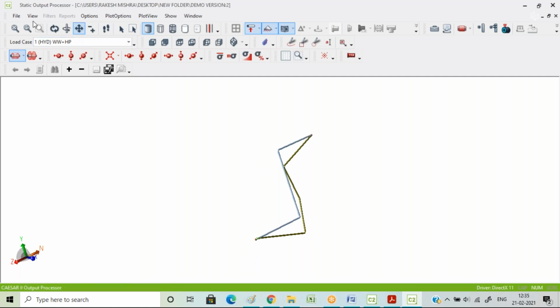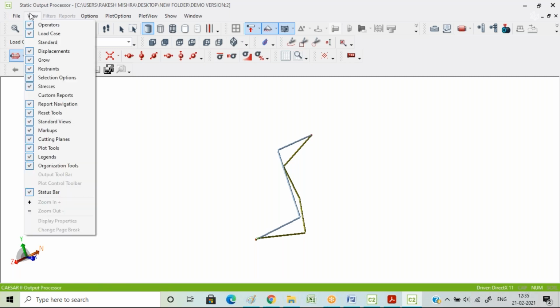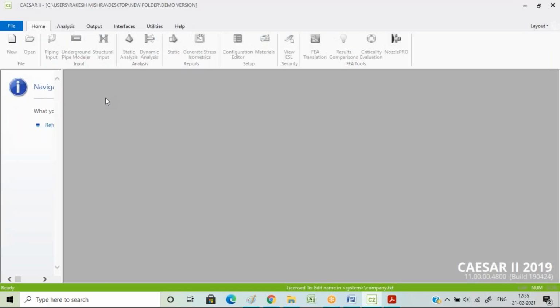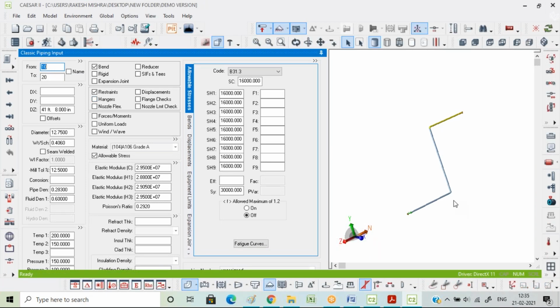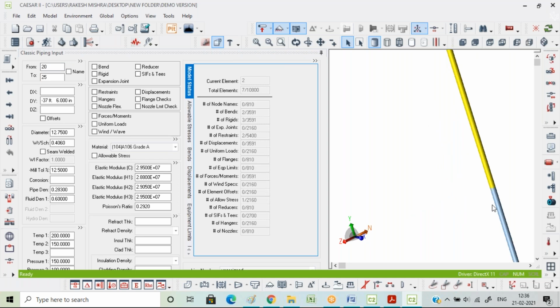Now if we go back to the system, earlier what we have used, the stop in between, the three-way stop. If we place that same stop right now over here, this will completely solve the issue. And the movement that we are seeing, that the complete pipe is collapsing somewhere over here, will be completely resolved.